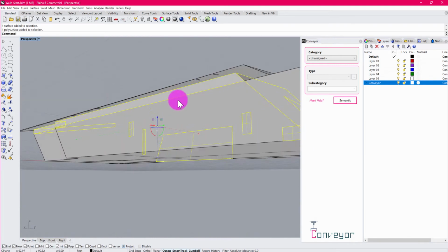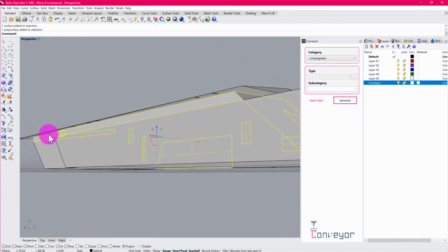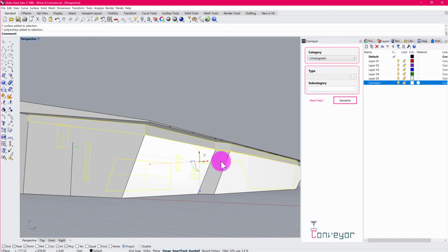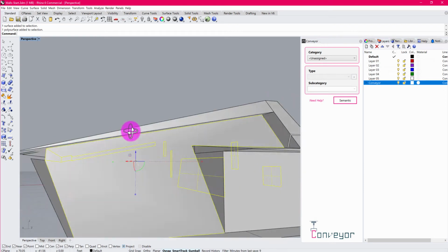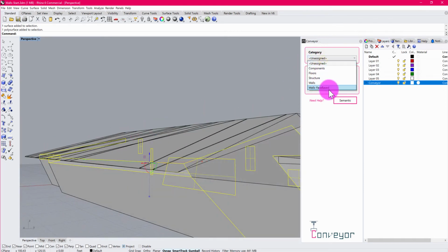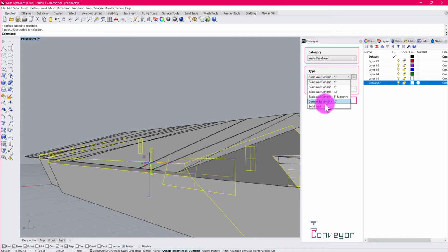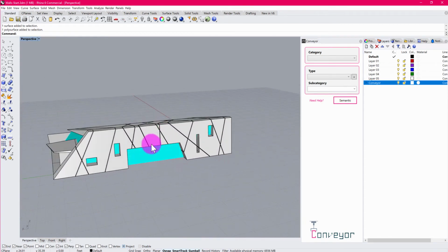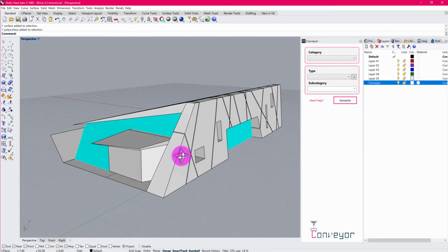You can see that's also connected along this edge here, so you can envision that this is going to be glass running along the edge where this masonry wall comes up. It's then going to have a glass reveal that then touches into the roof. So I'm going to make this a wall face-based, and then I'm going to give this, instead of a basic wall category of the solid wall, you can see that I have this curtain system, a 5-foot by 10-foot curtain system that I can apply to the object. So now we have that type of classification. So what we can expect is that a curtain system is going to be applied to these surfaces.